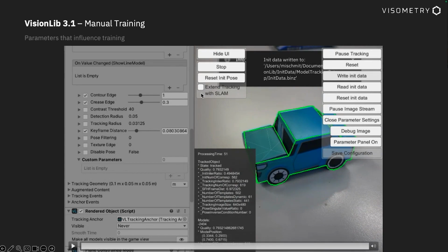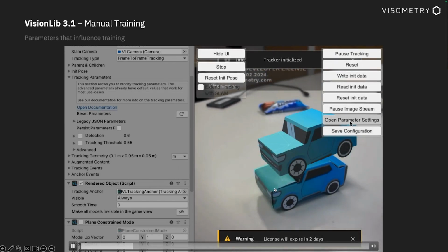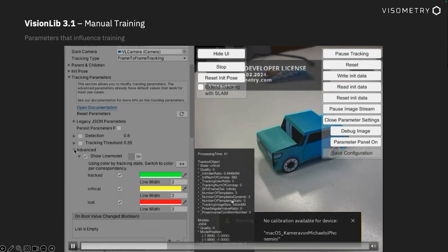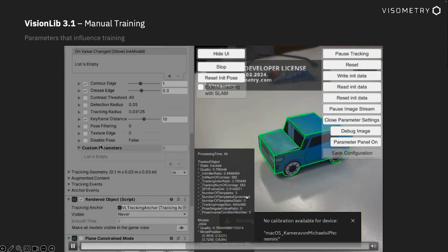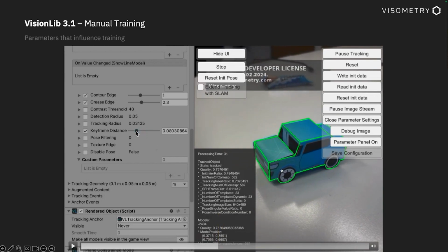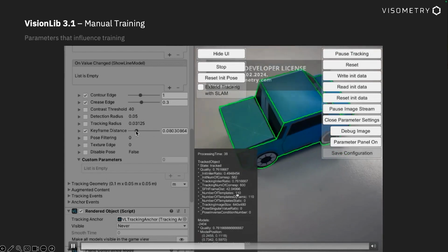At the beginning of this video, I'll jump back to the start. You can see that there are not very many templates collected while we are still using the default value for it. I didn't move the camera very much, and we only created about three keyframes. But when I move it down to 0.08 millimeters min distance, then it will collect almost every frame here.